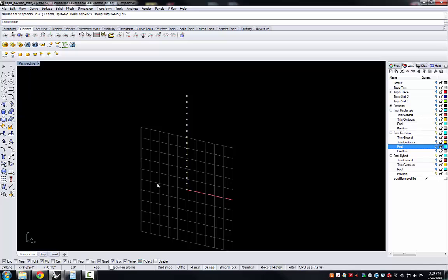The rule for the depth of treads, the part that you step on a stair, is that they should be around 11 inches, perhaps longer. And in fact, as your risers get shorter, the treads should get longer in order to accommodate the human gait.